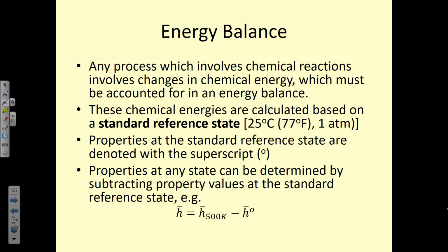And then properties at any state can be determined by subtracting their property value at the reference state. So if we wanted to know the actual enthalpy value at some temperature, we would just calculate or look up the enthalpy at that temperature and then subtract off this reference value. So it's similar to what we've done before with entropies.